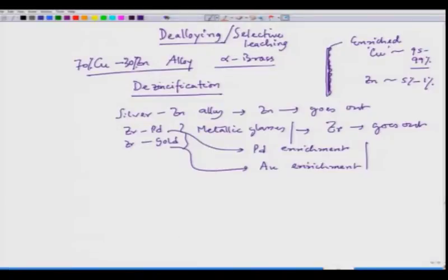But interestingly, as we have talked about in the first lecture, this de-alloying can be used in a positive sense. Nowadays we are trying to make porous structures, and of course nanoporous structures. The size of the porosity is in the nanometric range, and these porous structures can be used as a very good catalyst, or they can be used for active surfaces for many other purposes like medicines and drug deliveries and all those cases.